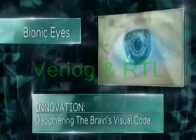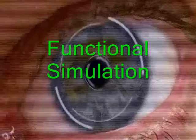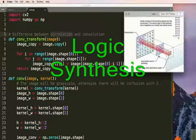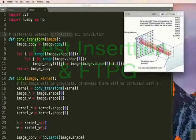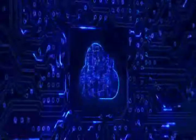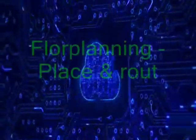The RTL behavioral or functional simulation of the VHDL code. The logic synthesis, followed by test insertion and ATPG. Then the post-synthesis or gate-level simulation, and finally floor planning and place and route.